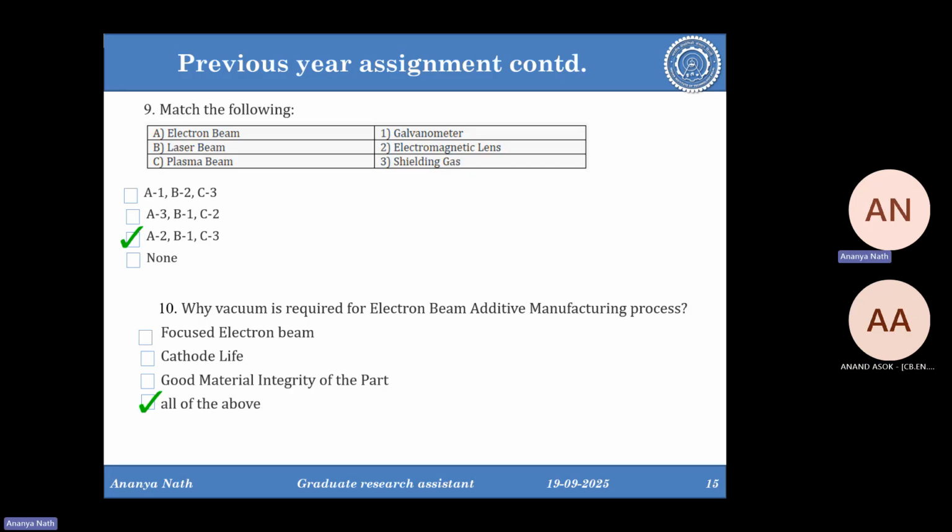Okay, so the electron beam is a beam made of electrons. In case of laser AM process, if you remember, we were focusing the laser using the plano-convex lens. It's basically the convex lenses, F theta lens or telecentric lens, whatever you need. But you have a physical glass lens to focus a light, and laser is a light beam. But electron beam is not a light beam. Electron beam is made of electrons.